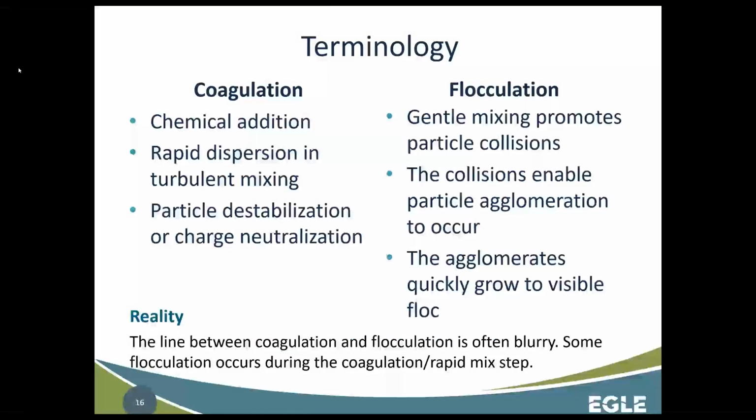All right, so before we move on here, I want to just spend a few minutes on terminology because various textbooks and folks that you talk to might draw the line between coagulation and flocculation in a different place. I just want to make sure we're all on the same page for this presentation. So for the sake of this presentation, we're going to look at coagulation as the chemical addition, the rapid dispersion or rapid mix, particle destabilization, which sometimes is also referred to as charge neutralization.